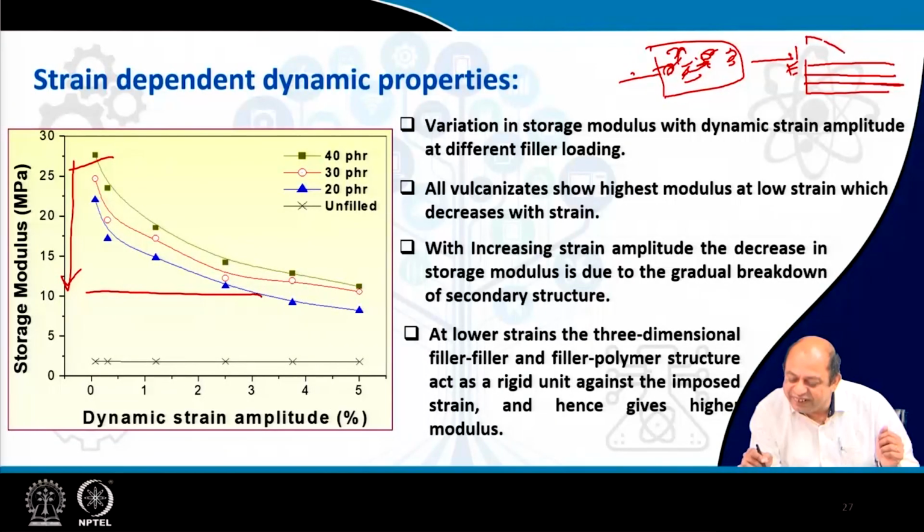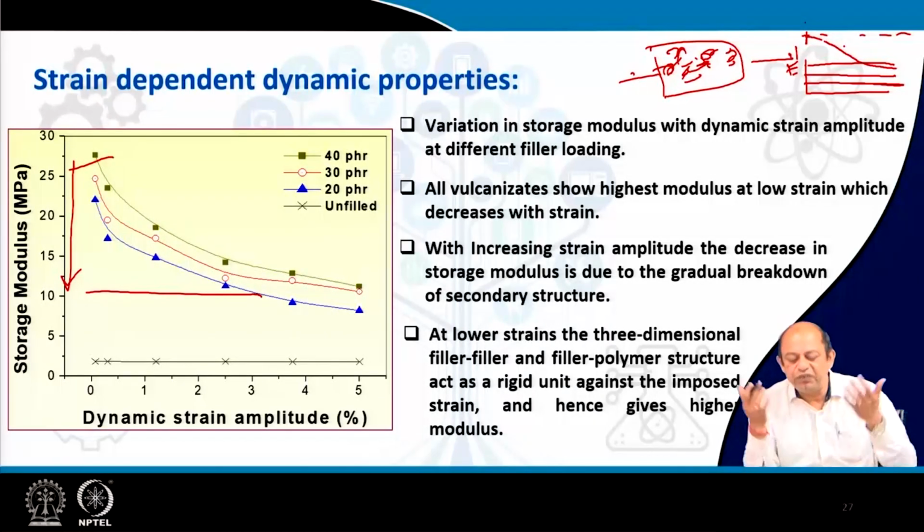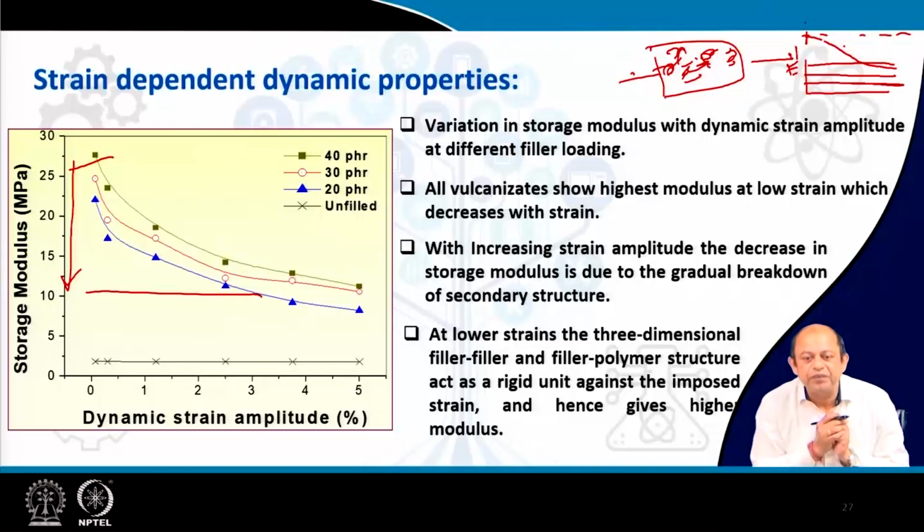It actually breaks down, and this is due to the aggregate-filler interaction part. So, you can measure how much is the filler interaction in the polymer. That ultimately gives you a signature up to which percolation limit of filler you must add. Otherwise, afterwards you may have gross deterioration of some of the properties. So, this DMA enables you to grossly understand what is happening in terms of filler aggregation in the matrix.